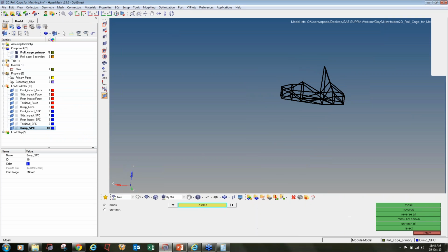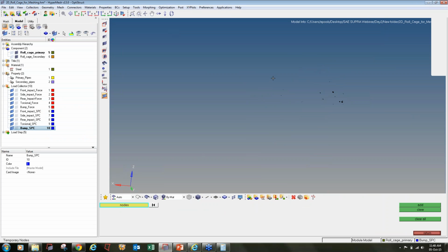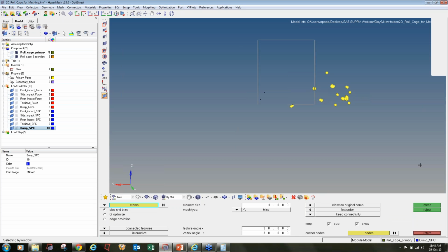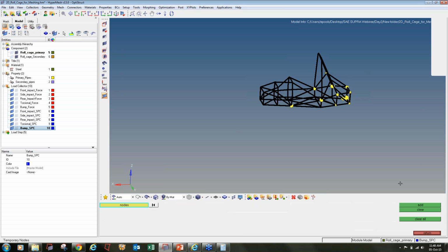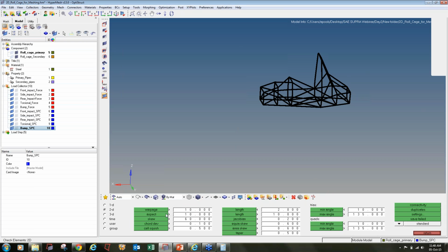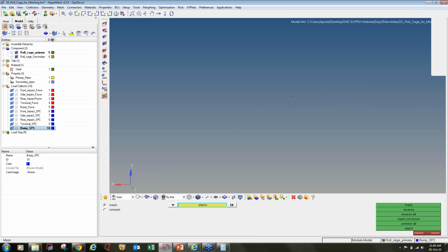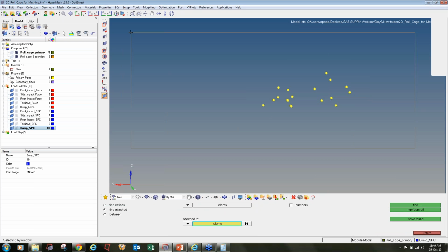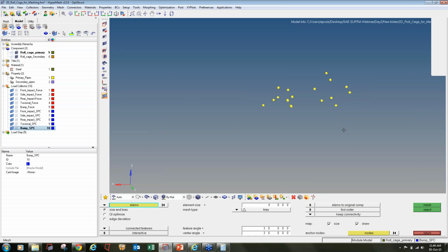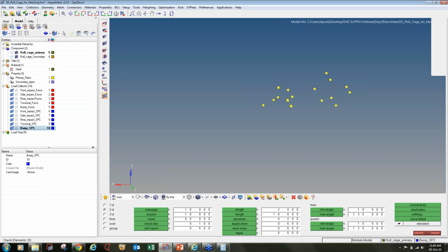So go to save field, mask, elements, retrieve, reverse, mask, shift F2, shift F5, find attach, F12, mesh, return, unmask all, then F10, aspect ratio, skew, save field, mask, elements, retrieve, mask, reverse, shift F2, add, shift F5, F12, mesh, return, unmask all, work page, aspect ratio, skew.